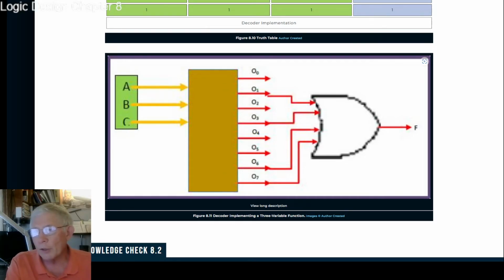The chip enable becomes your data in, and this is how you could use this to demultiplex a signal coming over from an 8-to-1 multiplexer. It can be used in that manner, but not always. You also have to, of course, send over the 3 control lines or have them generated at each end with some kind of very special synchronization, like using a satellite signal or something.